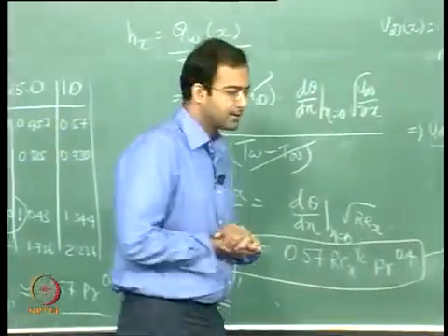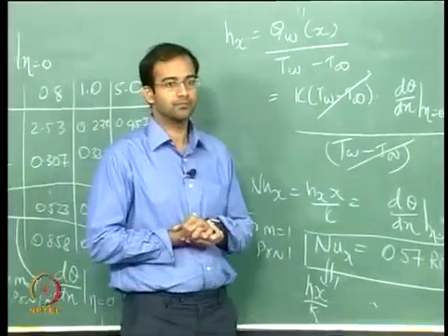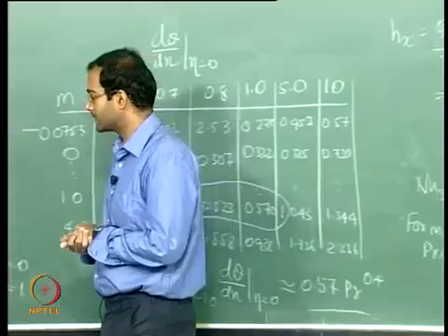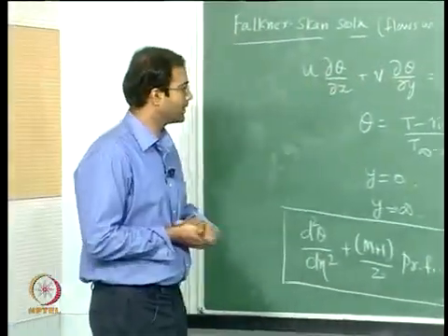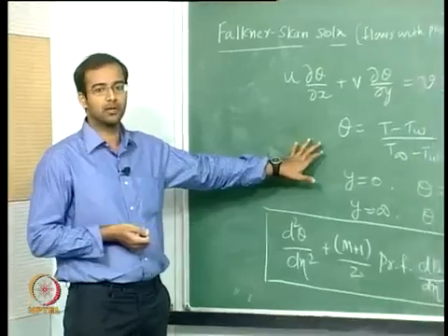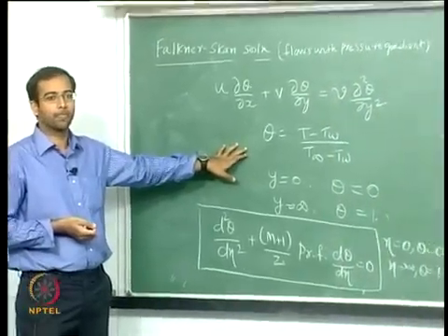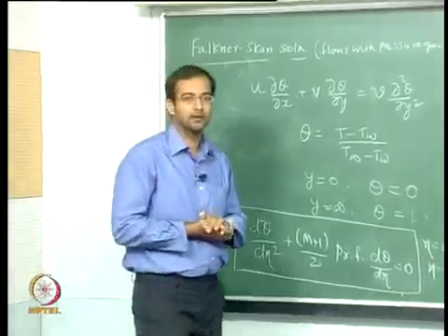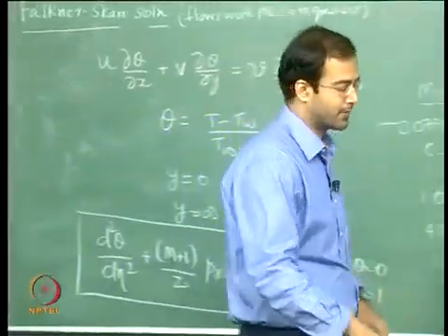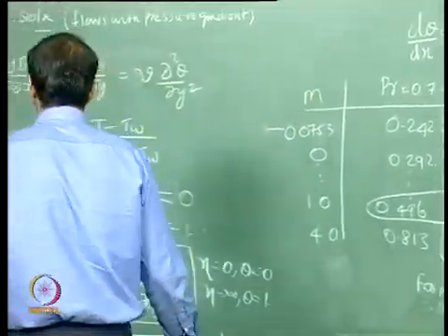The same way you can also do that for a sphere, for the case of 3-dimensional wedge flows. Whatever we were discussing so far are two-dimensional wedge flows. The same two-dimensional wedge flows can be transformed using what is called Mangler's transformation.